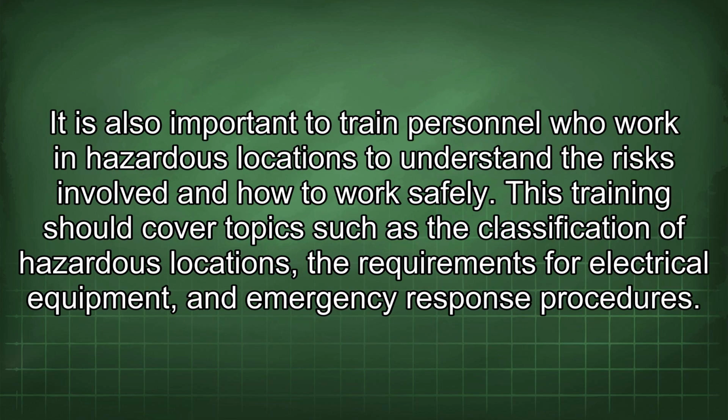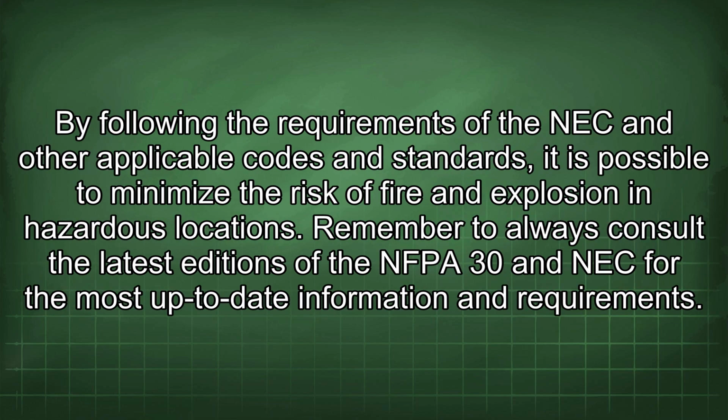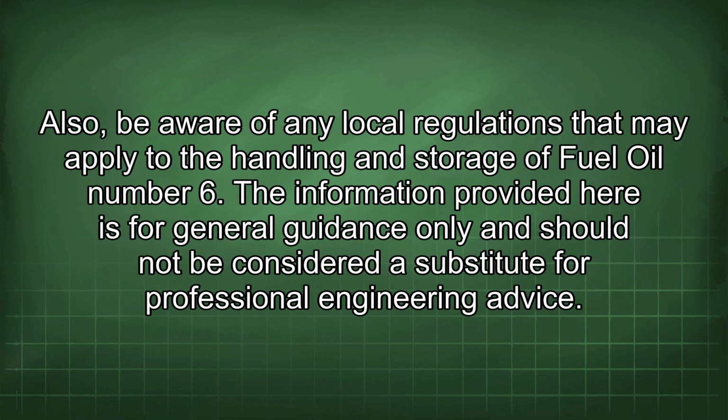It is also important to train personnel who work in hazardous locations to understand the risks involved and how to work safely. This training should cover topics such as the classification of hazardous locations, the requirements for electrical equipment, and emergency response procedures. By following the requirements of the NEC and other applicable codes and standards, it is possible to minimize the risk of fire and explosion in hazardous locations. Remember to always consult the latest editions of the NFPA 30 and NEC for the most up-to-date information and requirements. Also, be aware of any local regulations that may apply to the handling and storage of fuel oil number 6.